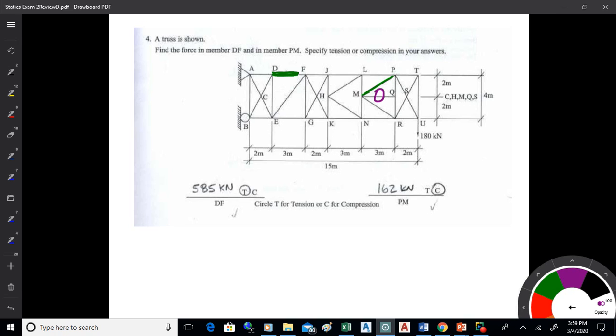I want to point that out because on a zero force member, if you look at one side, sometimes you can't see it at all, but you can see it on the other side. So what about FG or GF? It's too much going on for that one. Five things at F, four things at G, just too much. You can't assume anything there because there are so many unknowns.